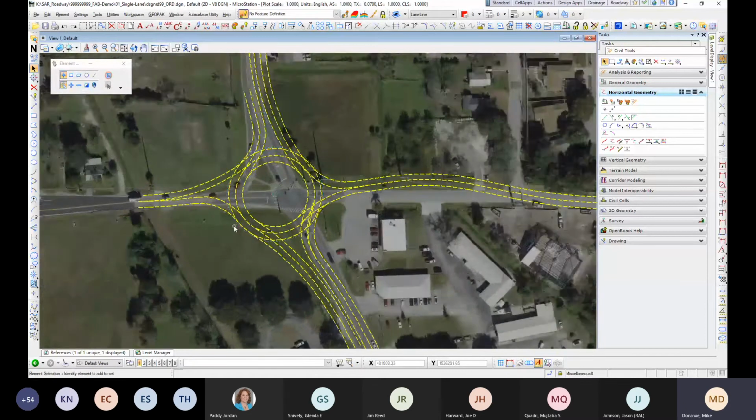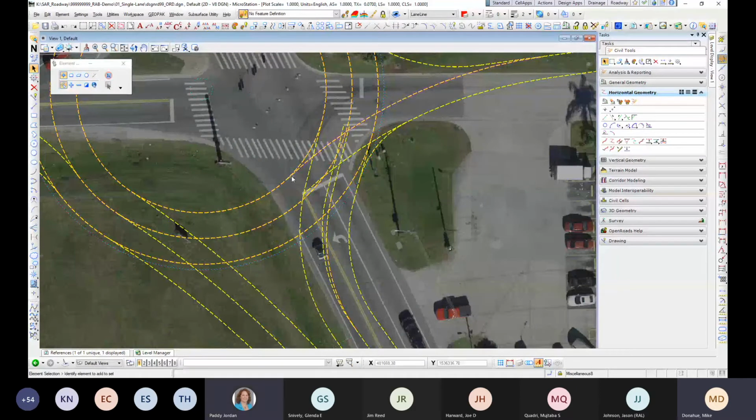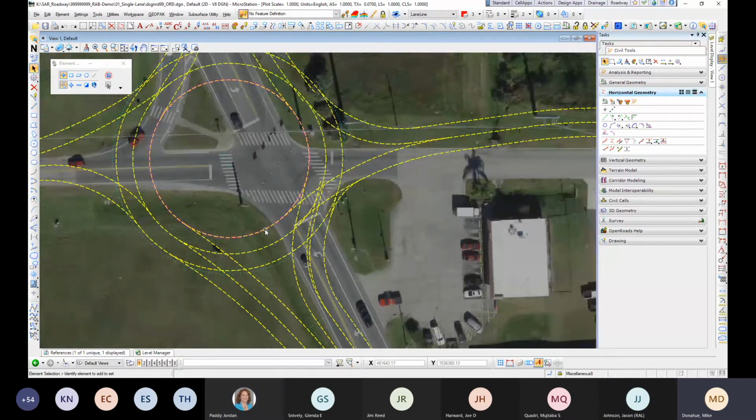And as I get into the roundabout, for the most part, in these areas where your road comes into the circulatory roadway, it's just profiling lines. And then once you have your lines profiled the way that you want them, you'll run linear templates to fill in the voids for your median curb and probably triangulate your last little piece of sod in the median from back of curb to back of curb. And then you could run a component of pavement that'll have your asphalt and base and stabilization depths assigned to it from the inside to the outside. But all the vertical control, at least what I've done in the past, has been just by profiling the lines and then grabbing all that and triangulating it, providing depth.